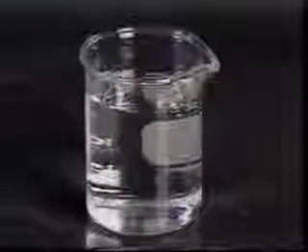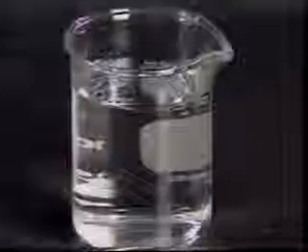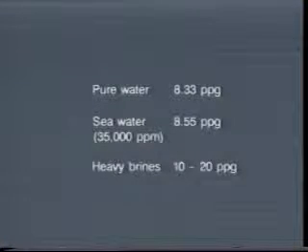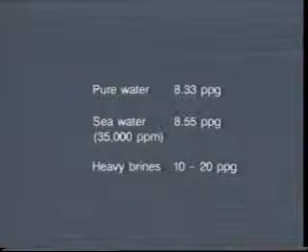The discovery of the benefits of clean, solids-free completion fluids has led to the development of high-density salt solutions for use during the perforation of a well's casing. Pure water weighs 8.33 pounds per gallon, while seawater, with a salt concentration of about 35,000 parts per million, weighs about 8.55 pounds per gallon. Clear solutions of chlorine and bromine salts of potassium, sodium, calcium, and zinc can be used to achieve weights from 10 to 20 pounds per gallon. Keeping the salts in solution at the various temperatures encountered is the primary challenge in the formulation of these products, and they are used primarily in the completion phase of the drilling operation.